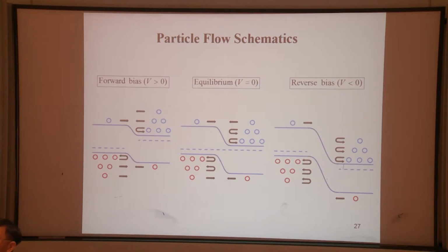Okay, put it down. Current. Increase the current, yes. Do you think the forward bias will help the PN junction to induce increased current? Yes, of course. But I still need to ask, right? Has anybody thought that if you are forward biasing the PN junction, the current will not increase or even reduce? Anyone? No. Very good. Because in the forward bias, you will increase the population of the electrons, the majority carriers that can overcome the barrier. So the more you bias, the more diffusion current you get.